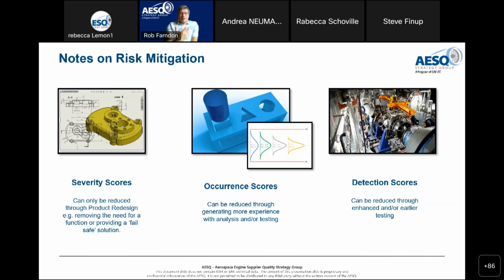It's about designing out those high consequence failures before they get to the point at which you have to worry about detection. Detection is the last refuge of the scoundrel. Okay. You need to be able to demonstrate you've done as much as possible to design out the error before you put a test in. Although some testing is a good thing to do, clearly. It's good value.